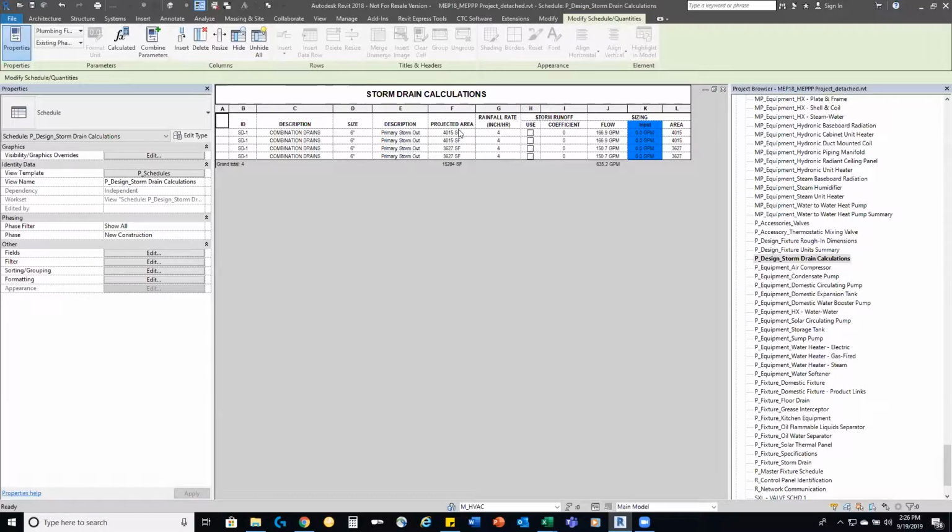This also allows you to relocate rainwater leaders in the event that you have to. It gives you the most flexibility in essence. But when you come here and you enter that square footage data, that then becomes a piece of information that is flowed down the pipe. So as I take different rainwater leaders and connect them to a riser, I can then click on that riser and see exactly how much square footage that riser is responsible for, thus helping me size that riser.